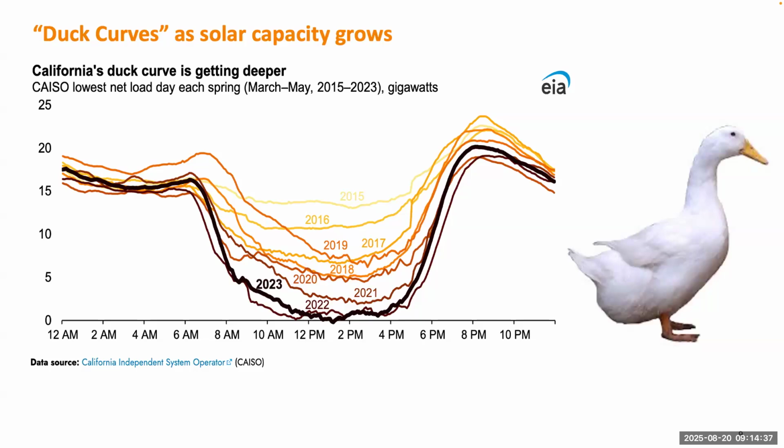So in the late afternoon, around sunset, the solar generation will largely decrease, and then you'll need a conventional generator to back up the reduction of solar generation. That will cause a very large slope. So you need a conventional generator to ramp up the power at a very high speed, such as more than 10 gigawatt in 3 hours. That is almost at the limit of most conventional generation.